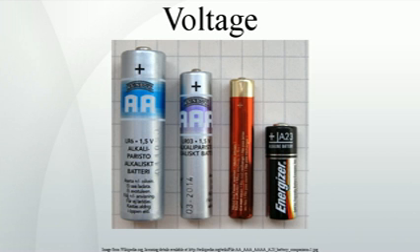In such a system, the work done to move water is equal to the pressure multiplied by the volume of water moved. Similarly, in an electrical circuit, the work done to move electrons or other charge carriers is equal to electrical pressure multiplied by the quantity of electrical charges moved. In relation to flow, the larger the pressure difference between 2 points, potential difference or water pressure difference, the greater the flow between them, electric current or water flow. See electric power.